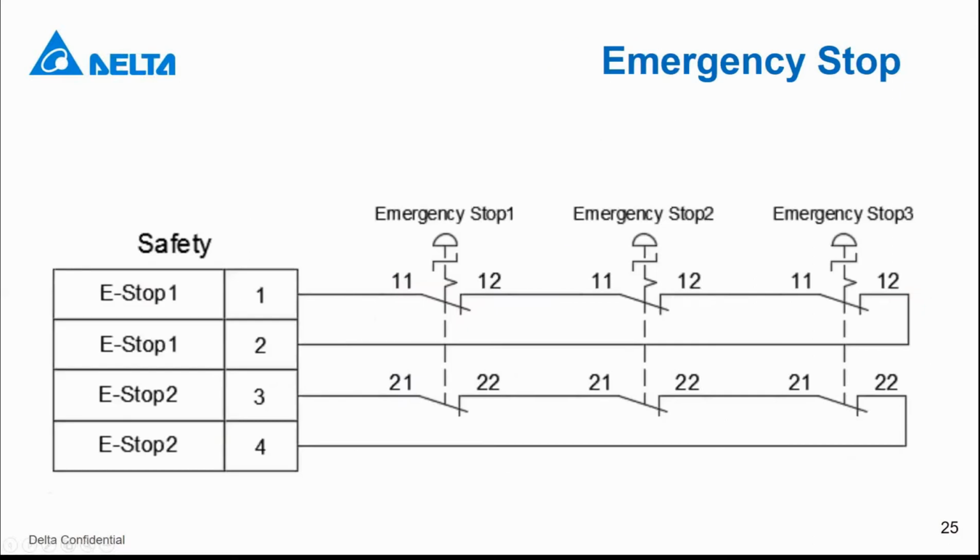And next is the emergency stop. This must be connected. Sorry. It's a 2-channel emergency stop. Both channels you need to connect, then it will work. And if you want to connect more emergency stop buttons, then you can connect them in parallel like this.